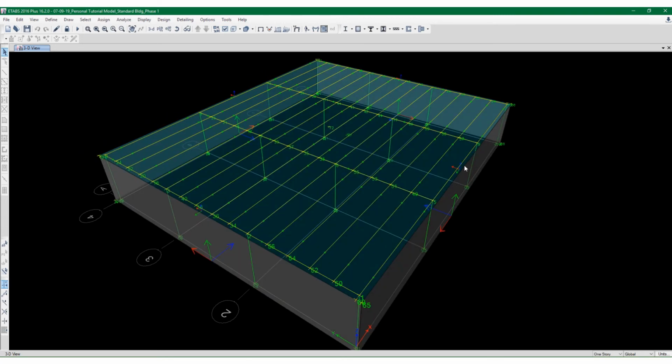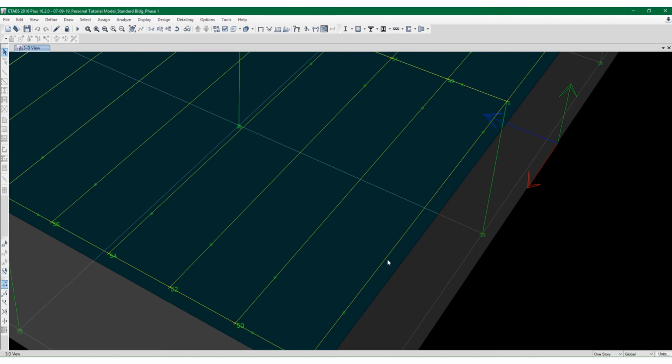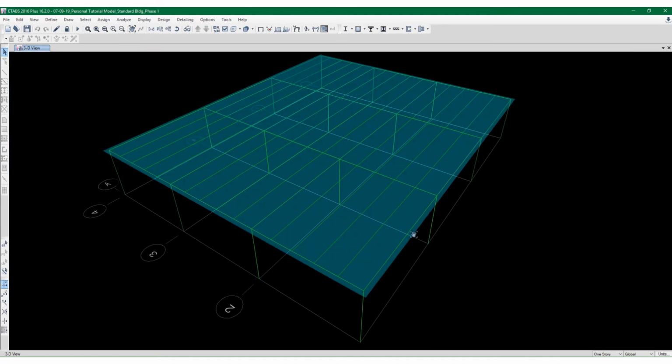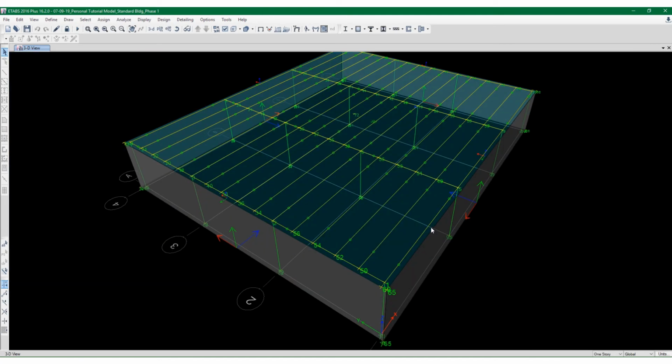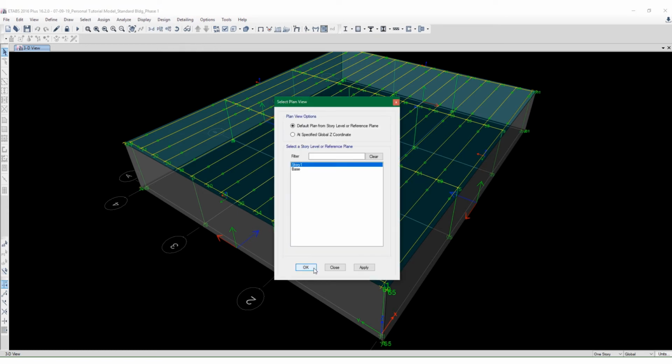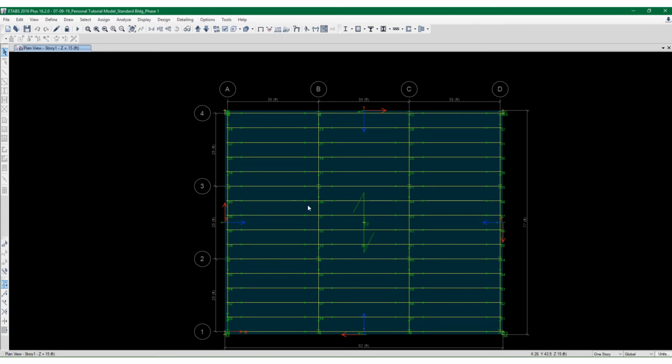So what I decided to do was to actually model in that angle, or a plate, with the stiffness of a 1/4 inch of steel, and place it along the perimeter. And so you can see what I'm talking about here.